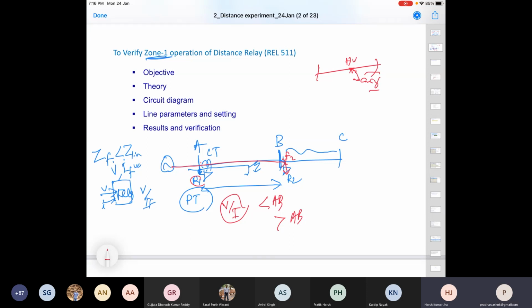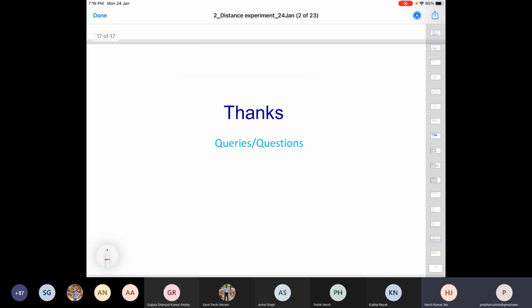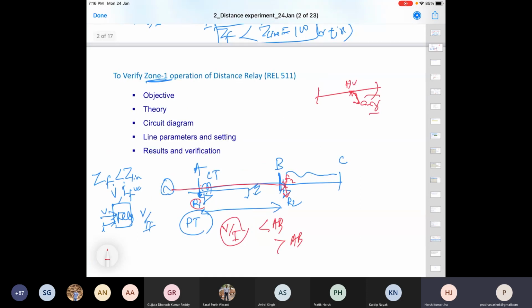So this will be a conductive medium, and that arcing path has a certain resistance, and again it goes to the ground, to the system grounding, transformer grounding or so. So this grounding path has a certain impedance. The tower through which it passes also has tower footing resistance, and these are different factors which account for the arcing resistance, or what we call the fault resistance path, and that will be added to it.